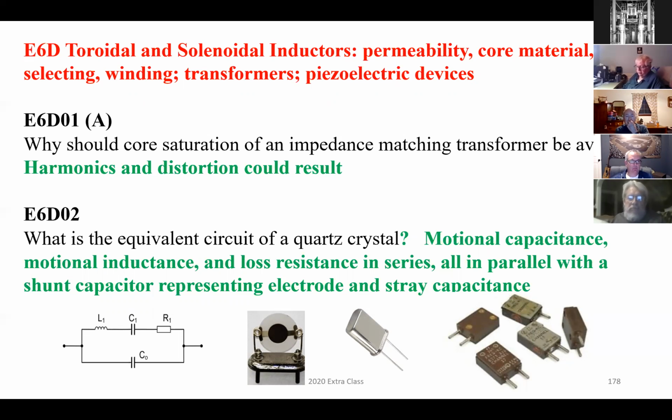Okay, number two, what is the equivalent circuit of a quartz crystal? It's going to be A, motional capacitance, motional inductance, and loss resistance in series, all in parallel with a shunt capacitor representing electrode and stray capacitance. That's a mouthful.